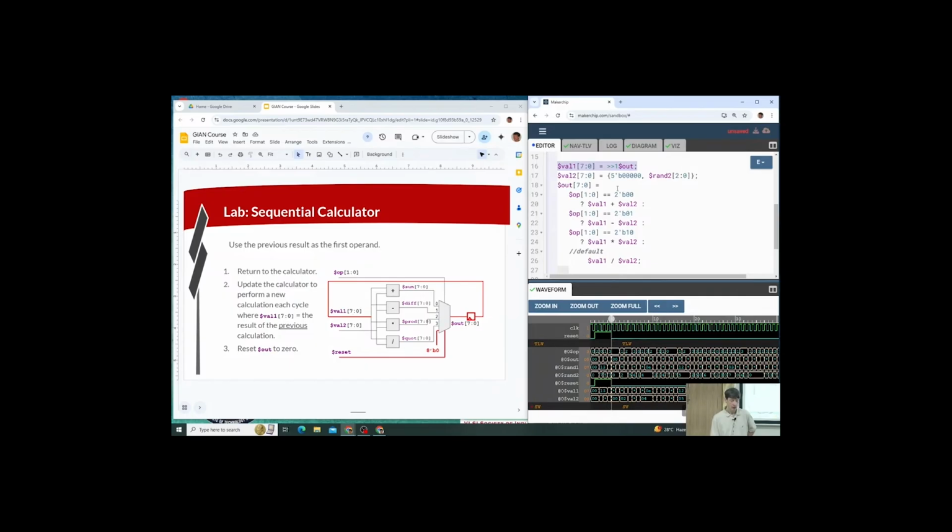The other part of this is reset. So for reset, the logic as drawn here is factored into this mux. Essentially, reset you're always factoring in as a multiplexer in front of a flip-flop. We already have a multiplexer in front of the flip-flop, so we'll just include it as one of the choices for that multiplexer. You could define a separate multiplexer right here. It would do the same thing. So I'm going to define it all in that multiplexer.